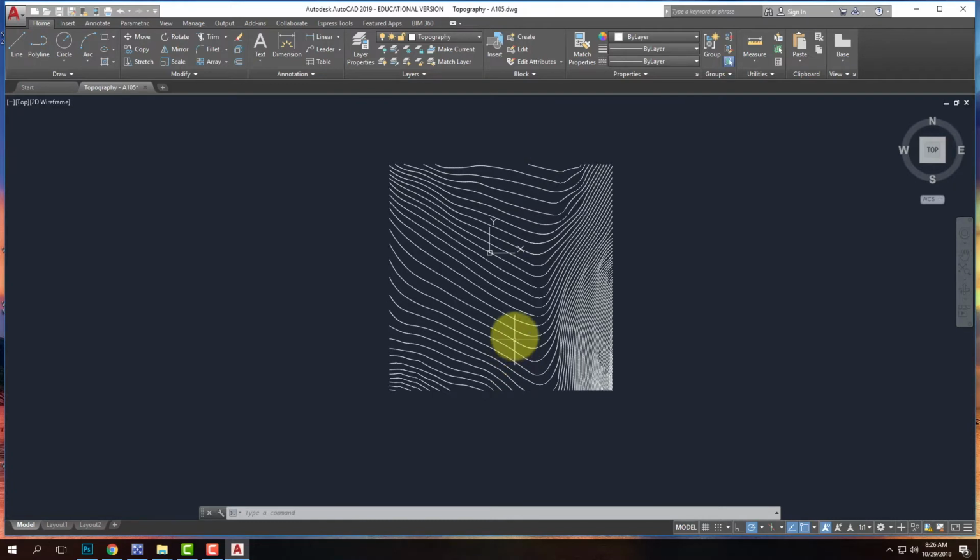These contours are at 1 foot intervals, so every one of these steps up by 1 foot. The lowest part is up here at the top, so it's actually sloping away from us. So from south to north, it's going downhill. The highest point in this whole drawing is up here in the lower right corner, and so everything else is sloping downward. Does that kind of make sense to everybody? I just want to emphasize that everything's sloping down.